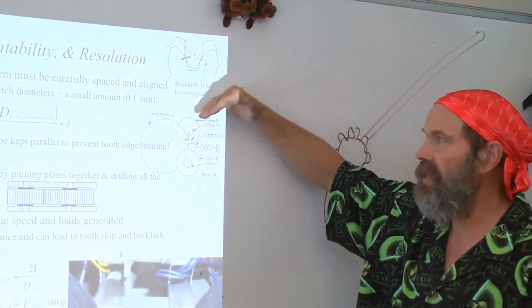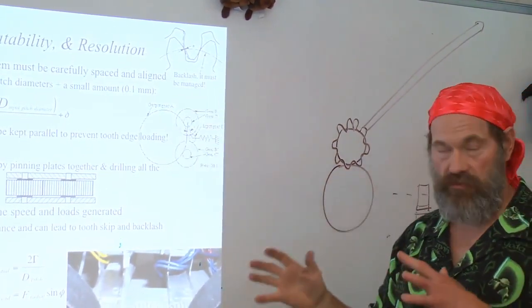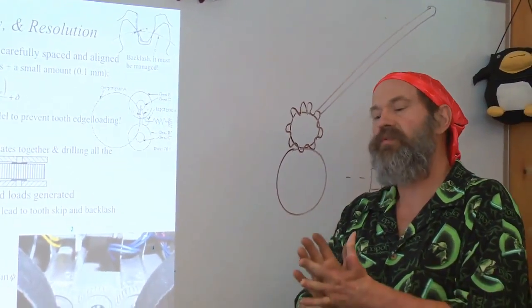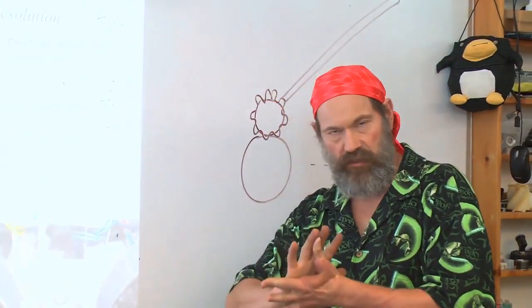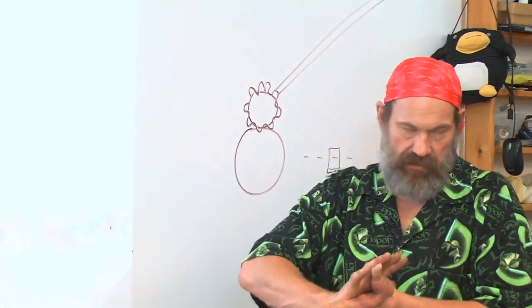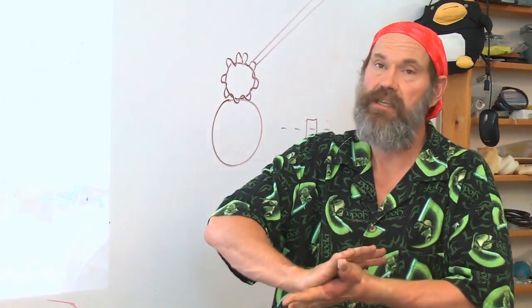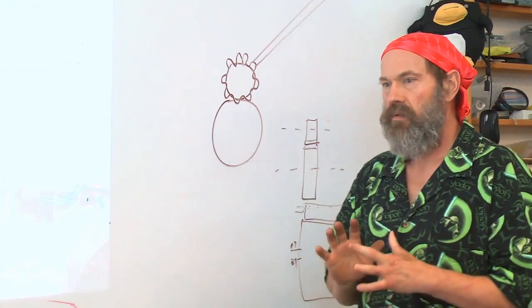You have to use a second set of gears, and there's many different types of systems to do this in terms of two different sets of gears. One transmits torque in one direction, one transmits torque in the other direction, and they're either spring-loaded or fixed distance separation, but still preloaded by the inherent elasticity in the system to take out the backlash in gears.